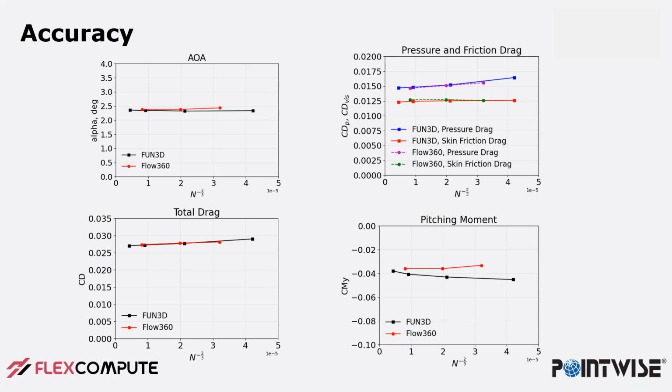And this is, again, also with different meshes, right? So we have a mesh difference, and we have an algorithm and numerical scheme difference. So the result is going to be different. What you need to really look at is the so-called Richardson extrapolation. That is when you look at several consecutive flow solutions with different meshes, you can start to extrapolate to what the solution would be if I further refine the mesh. And in this plot, the reason we are plotting the x-axis as the number of grid points to the minus 2/3 power is exactly for the convenience of that extrapolation.